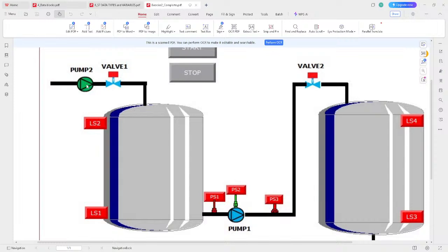You can see it here. So when I took the screenshot, this pump one was blue. It's on manual mode. So you have blue, blue. This one is black. This one is black. Okay? Blue. So these are the four states. And if there is any error, maybe dry run error or whatsoever, everything is going to be red.